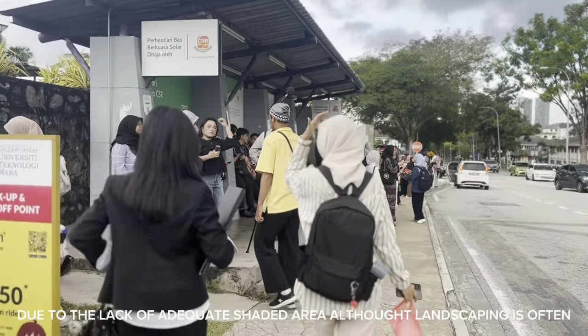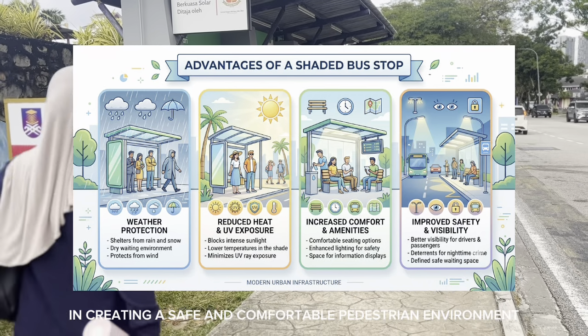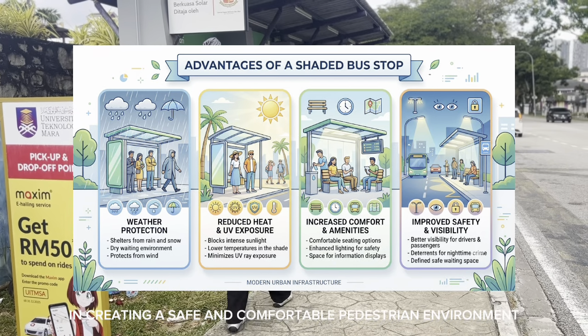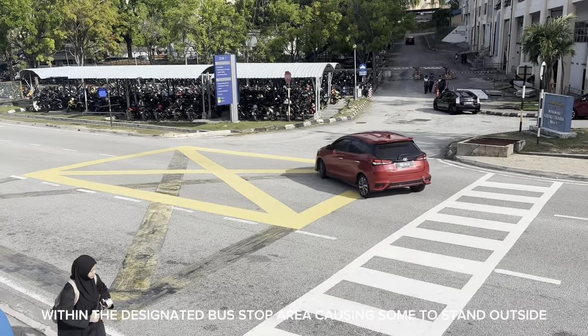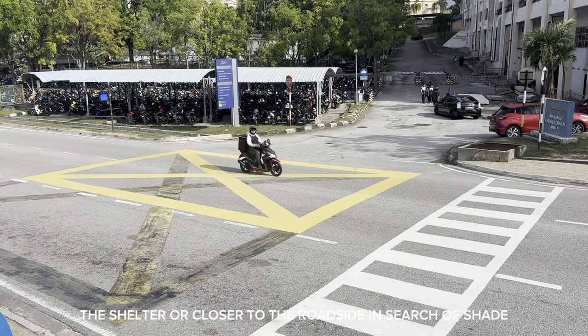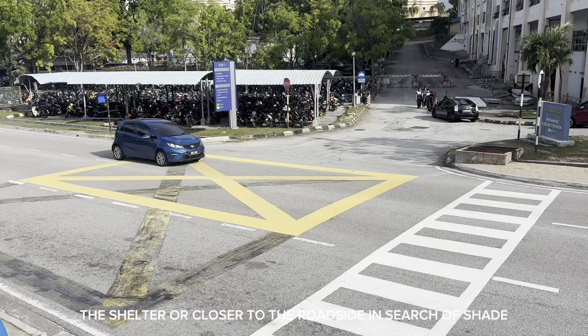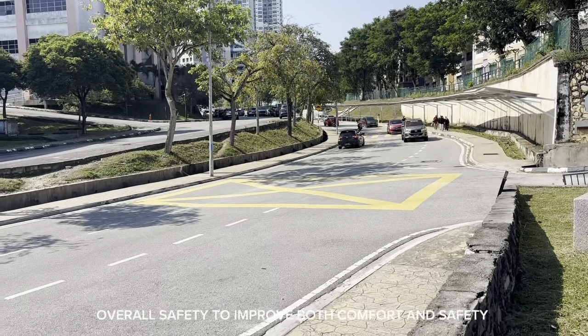Although landscaping is often associated with aesthetics, it also plays an important role in creating a safe and comfortable pedestrian environment. A lack of shade may discourage students from waiting within the designated bus stop area, causing some to stand outside the shelter or closer to the roadside in search of shade. This can increase pedestrian exposure to moving traffic and reduce overall safety.